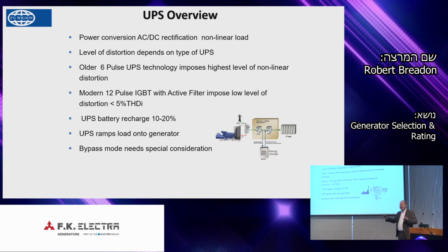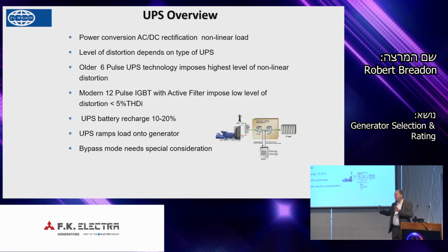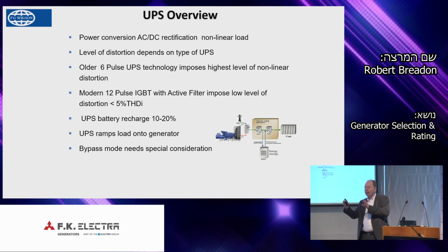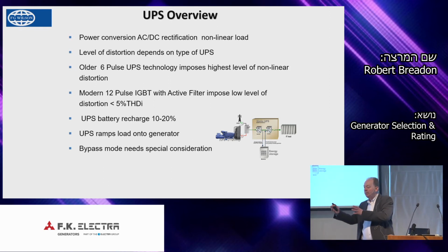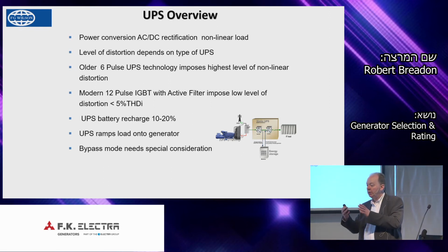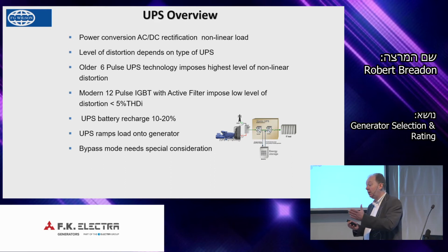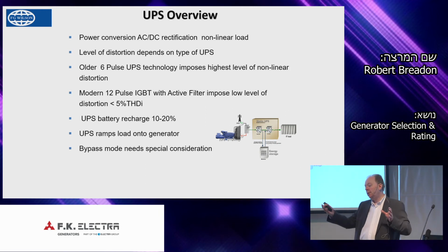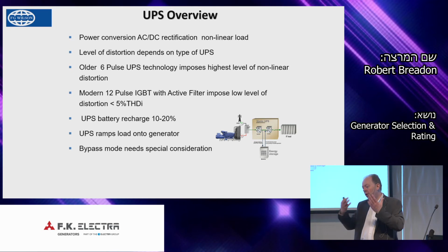So they set very tight guidelines. And I know of applications, probably in industrial areas where there's been so many buildings put in, and the customer at one stage, this is for a utility connection, had to either put active filtering in or find some means of limiting the non-linear load, because they wouldn't be allowed to connect, especially in a lot of process areas or where there's a lot of drives or non-linear load.